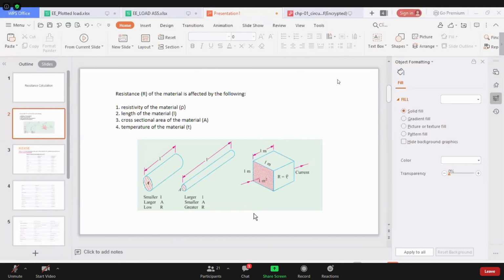Actually, our nominal voltage is 230, 210 is the lower extreme, and 240 is the higher extreme. So the nominal, the proper voltage is 230 volts. So why do we have an extension of 10 volts or 20, which is still okay? Why do we have 20 volts extension on the transformer rating?